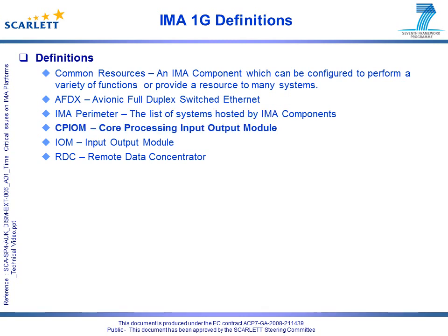CPIOM, Core Processing Input-Output Module. A processing unit with built-in I/O, primarily used on IMA 1G architectures. IOM, Input-Output Module. Additional I/O translation to AFDX, either for direct discrete or analog types, or for a system-specific LRU without an AFDX connection.